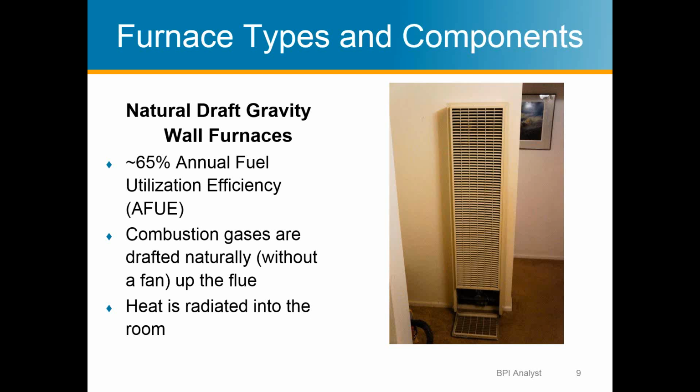so the heat comes over the heated plates inside the heat exchanger and heats the house, and then it keeps the hot gas away from the air inside the house, and the hot gas, the exhaust, vents out. So there's no fan used in this to help get the exhaust out, and that's really why the efficiency is so low. In these systems, they need a lot of heat in the exhaust, because heat rises, so if you keep a lot of heat in the exhaust, it rises better, and so it'll exhaust better.